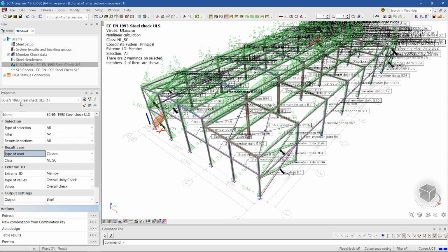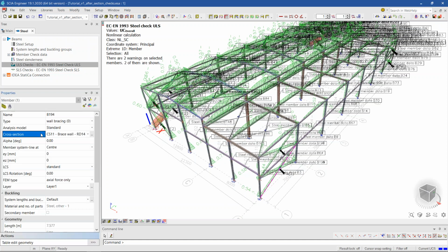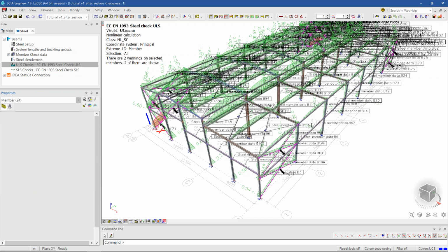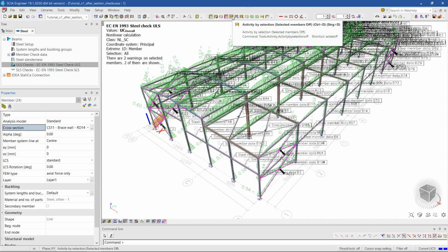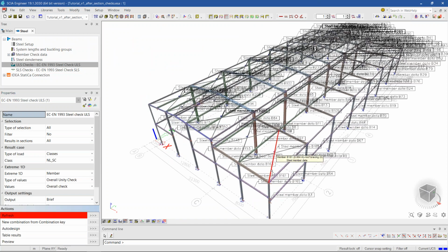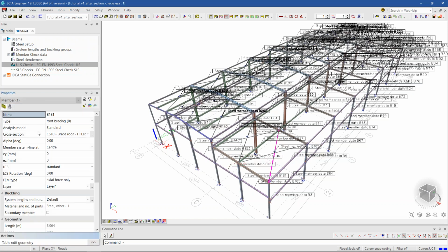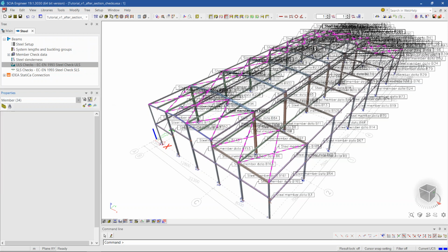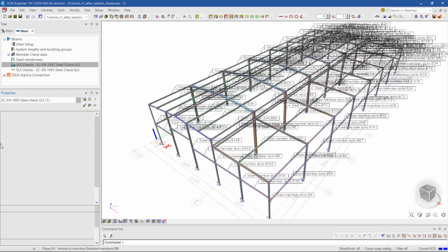So I'm not going to remove it because I will continue to work with the linear analysis for, let's say, when I'm just quickly running analysis to check what is happening with the structure when I change certain settings. And when I use this steel member data, then I don't get all these errors of buckling of my compression elements that are obscuring my view. And because of that, I will keep that data on these elements, and all the other data I will remove.